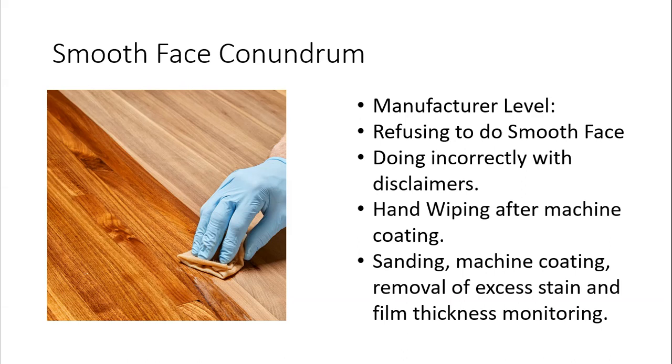Some of those stain guys are saying, look, we'll do the smooth face, but I'm not taking responsibility for the fact that it won't penetrate. We're not seeing any good results, but we'll do it as long as you write off that it's not our problem if it screws up. Some of them are saying it takes too long to dry. So as it comes off the machine, we're going to hand wipe it, and we're going to make that application more even. But if you haven't sanded that face, it actually makes it a thinner coat. So it's more even, but it's not going to last any longer.